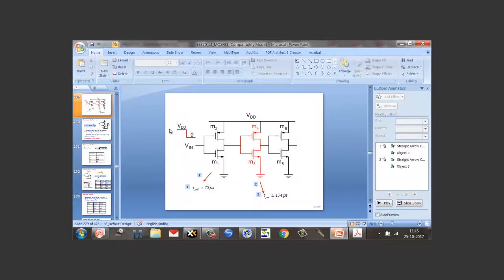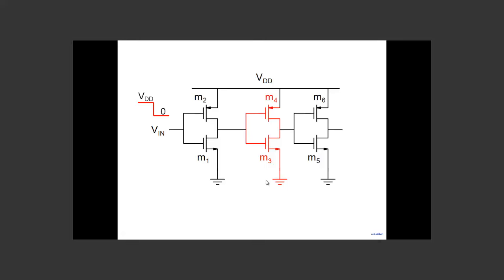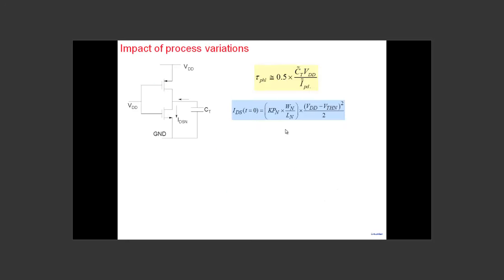So for example, for this 0.5 micron technology, what the manufacturer would do is take these inverters and make, let's say, a 31 stage ring oscillator. 31 such inverters connected, and they will quote the oscillation frequency of this ring oscillator. At what frequency is it oscillating? So that's a better measure, because each node is switching. This gets its input from here. This is also rising, falling, and all this. So that's more accurate. I'll come to that a little later on. We'll talk about this later on.